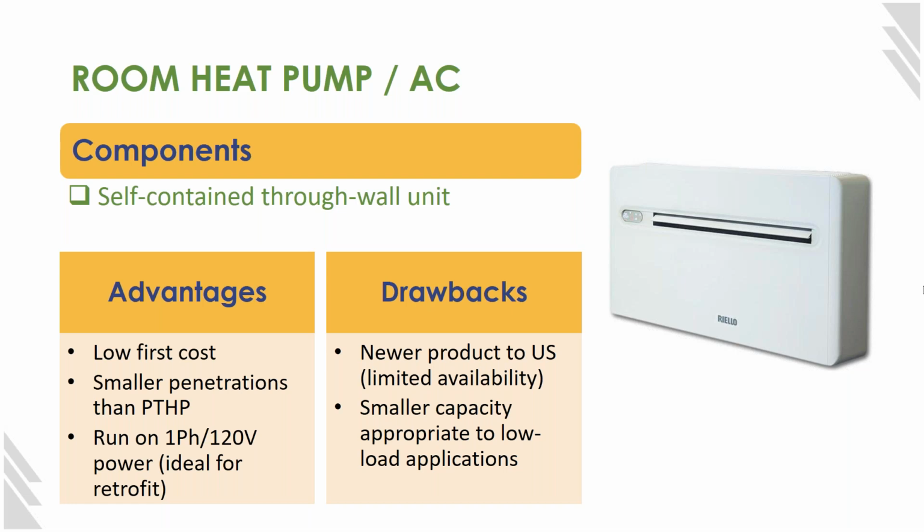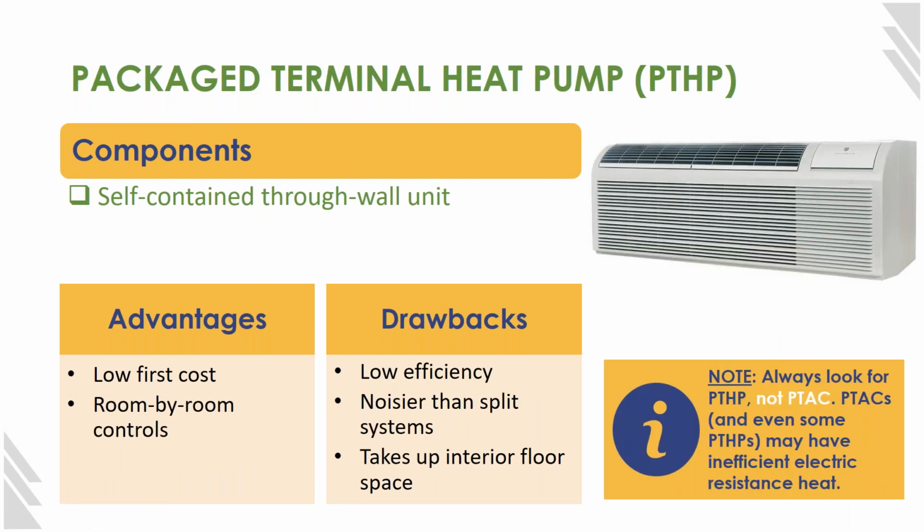Yeah, and then the next question pertains mostly to the PTHP, the through wall, is if you have any additional air sealing details or suggestions for that unit as it goes through the wall. So these are going to have a sleeve that goes into the wall, and then the unit goes into the sleeve. Yeah, you do have to air seal it. This is something that comes up on projects, and you just have to be careful and look at your details. I don't have any specific details handy for doing that.